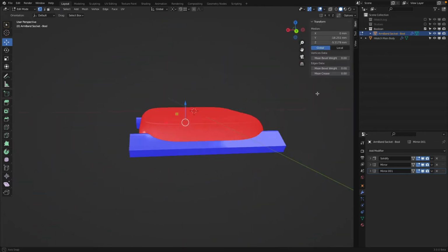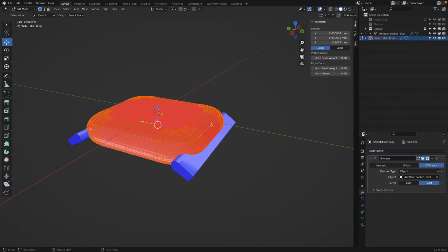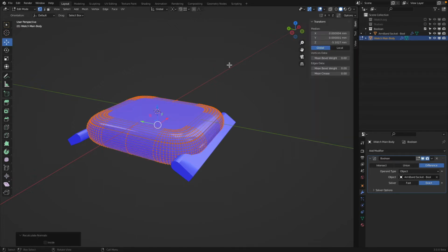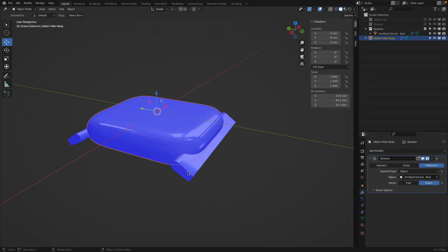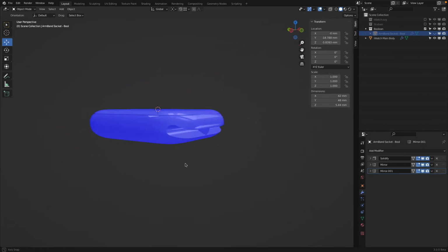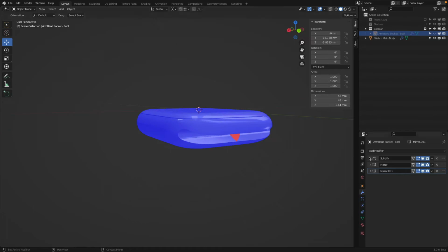Let's go to this, and oh yeah, there's a reason. So this is blue, this is red. It's not Democrats and Republicans or North and South, East, West, or ice cream and tomato sauce. It's inside and outside. So let's go to Shift N and flip this. Press Tab, select this, press H. Yeah, close. We have this thing in here. Okay, how do we fix this? So this might be the little offender, not a big deal. We can apply this. Very good.